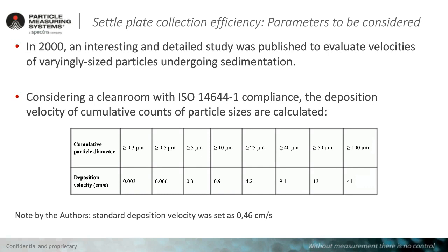In this respect, remember that the standard deposition velocity in EU GMP is set to 0.46 centimeters per second, or similarly in the FDA GMP.